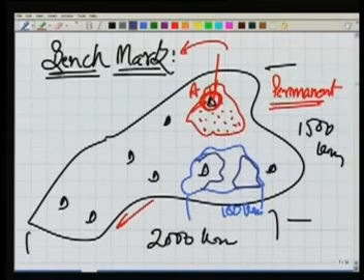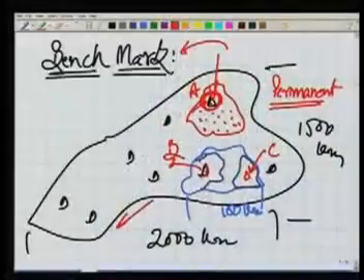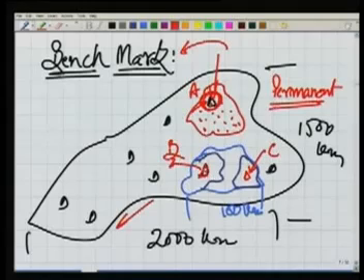So I would like to establish one more benchmark here with the help of the benchmark B. The benchmark at C is established first with the help of the benchmark at B, and later the survey in this area can be carried out using this benchmark at C. This kind of benchmark, which is established just for some temporary period, we say temporary benchmark, it's not permanent.